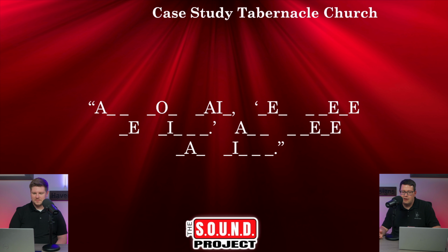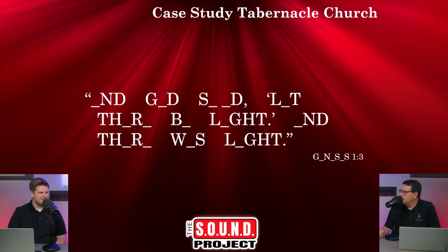Nope. Okay, I'm going to add the consonants in and take the vowels out. What about now? Yes, now you can. "And God said, let there be light." So you can start to read this when the consonant sounds are in. Now, this is just a visual example, but it works in the real world too: if the consonant sounds are controlled but not over-absorbed, then you can get good speech intelligibility.